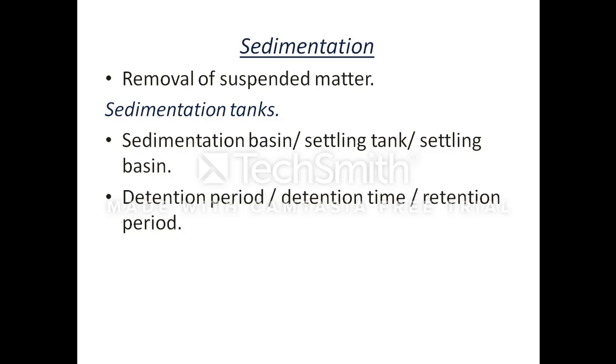But all these processes are not used together on the same water sample, because in some cases water may require only some of these operations. For example, for water that is more turbid but has less taste and odor, we can use sedimentation and filtration, but aeration may not be required.